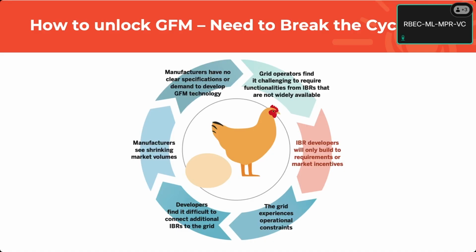So you're not wrong. If you operate a grid forming device at its current limit, you don't get that energy advantage, right? You can't get an under frequency response that's substantial, for example, but you do still get a small signal advantage.